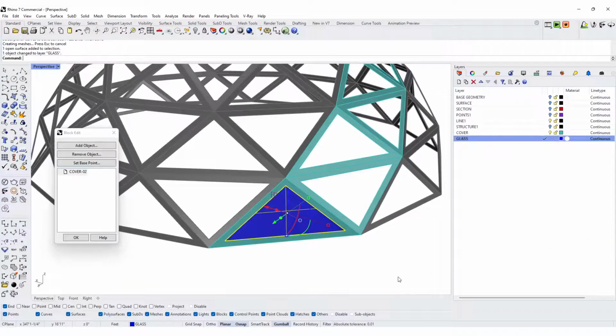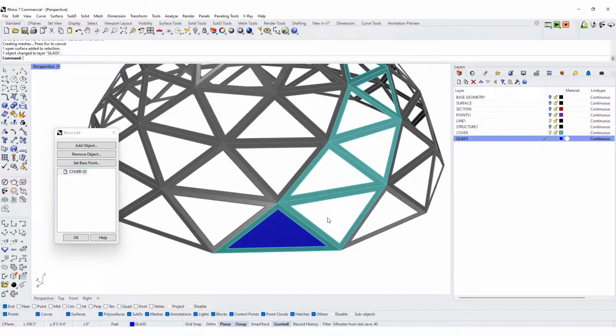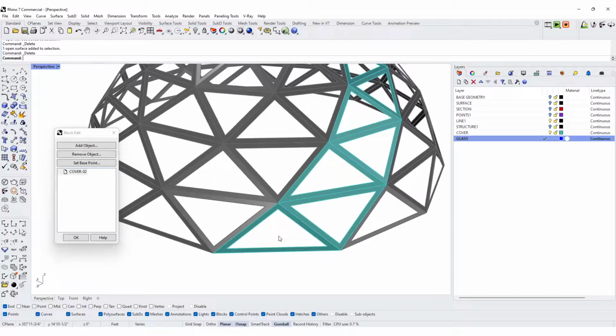And we'll go to change object layer. So depending on what technique you like to use best, planar surface between these three curves, or loft between this and this. So whichever one you choose, make sure that you're kind of consistent through all of them. So I'll just do loft.